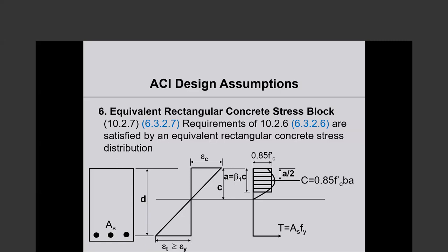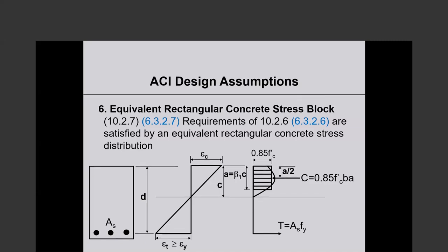It begins to matter as the section has more and more reinforcement, or as you change from a flexural section, a beam section, to a column section. You put more and more axial load on the section. Now the compression properties of the concrete become important. So remember these basic things, that as long as it is a beam, what the concrete does is relatively immaterial. It's the reinforcement that counts.